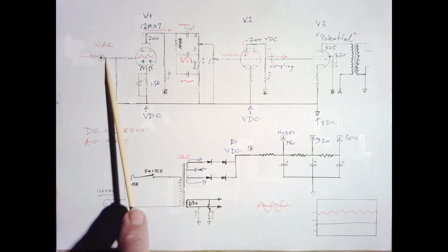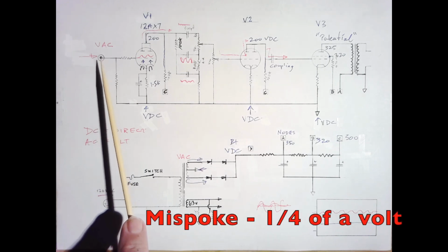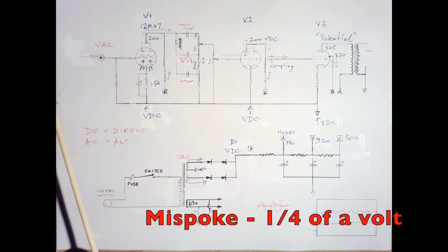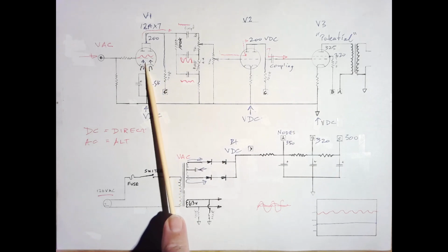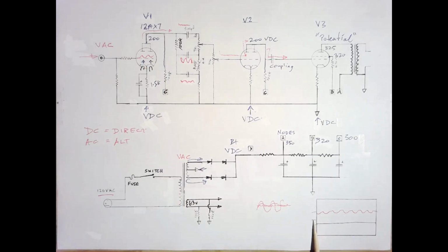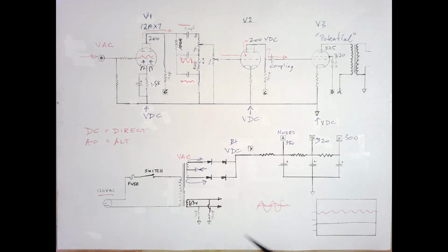Anyway, so what we're doing here is we're injecting our signal voltage of AC, which could be 1/4 of an amp, possibly less, possibly a little bit more, but not usually much more. We're injecting that in here, and it is getting a free ride on top of the DC. Imagine this is the screen on an oscilloscope, and it has two channels, and one of the leads is plugged into the DC, which is direct current, and it will give us a straight, flat line, because it's just direct. And it will read off at whatever the voltage is. The AC current, if we connect a lead up to an AC line, will always float. It looks like it's just sort of floating there above the DC current.